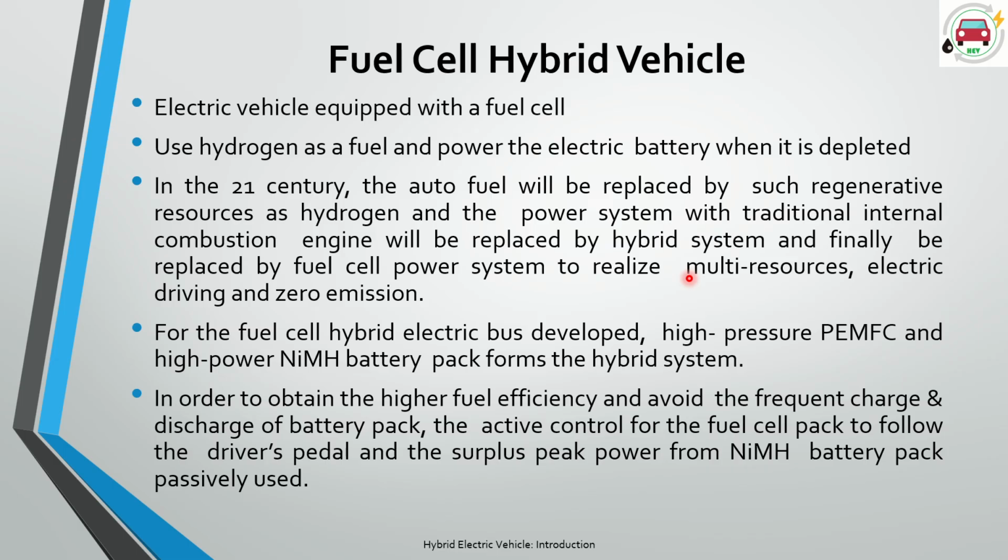If you can see here, there is higher fuel efficiency and frequent charging. Then we can have active control of the fuel cell, as well as the driver's pedal, and the surplus peak power goes to the NiMH battery pack that is used passively.